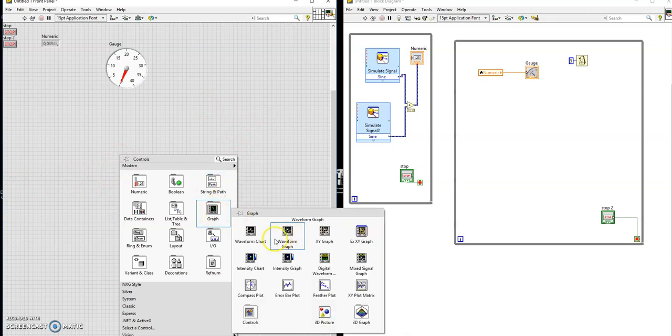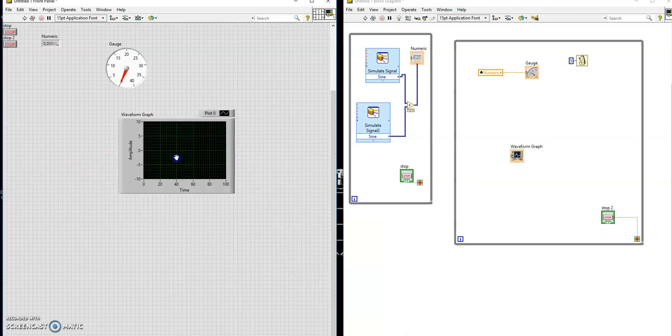We want to see it on a graph. We have to record values. Now remember, if you did this with a little book or in Excel, it means you have to measure the values, put them in an Excel sheet, and then take those 10 values or 1,000 values, then plot the 1,000. In this case, can you see there's 100 values? You want to plot the 100 values, so value 0, value 1, value 2, value 3. The moment you start doing this, you can't really control anymore, because you have to wait for those 100 measurements to be done to be able to display it.